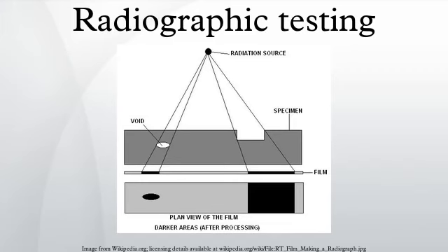Neutron radiographic testing is a variant of radiographic testing which uses neutrons instead of photons to penetrate materials. This can see very different things from X-rays, because neutrons can pass with ease through lead and steel but are stopped by plastics, water and oils. Since the amount of radiation emerging from the opposite side of the material can be detected and measured, variations in this amount of radiation are used to determine thickness or composition of material.